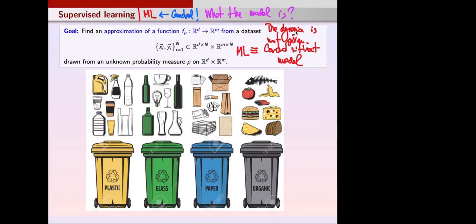And if you give me this model and you give me the matrices A for the dynamics and B for the control, then I can do, for instance, the Kalman rank condition, and I can tell you whether the system is controllable or not. But here there is no ODE.